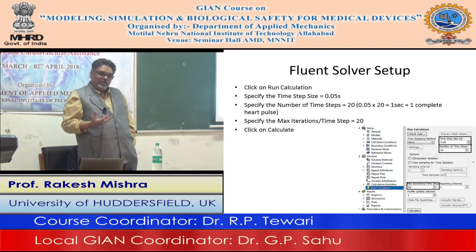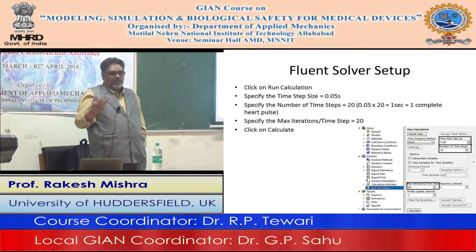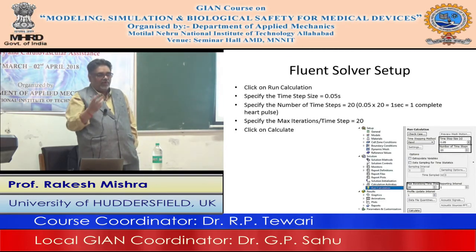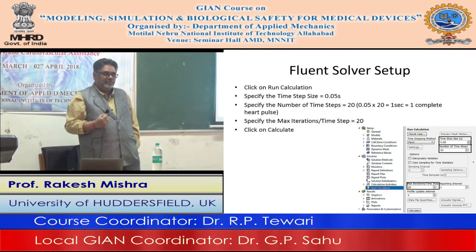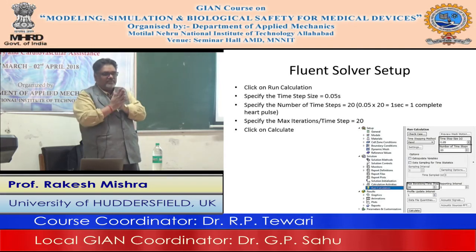But for a macro level description of flow, a reasonably big size description, time independence will be reasonably okay. But suppose you are trying to capture coherent structures, you are going to do LES and all that, then you need to ask which phenomenon you are looking for, and what the length scale and time scale for that are. For big scales, you carry out the mesh independence and the time independence test, and you will be reasonably okay.